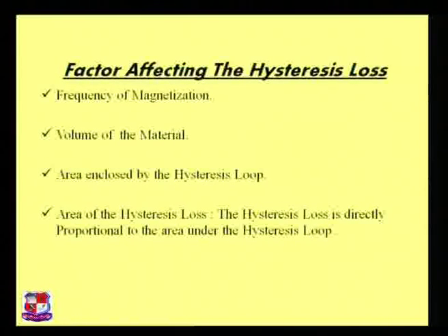Here we can see the factors which affect the hysteresis loss. The first factor is frequency. If the frequency changes, the hysteresis loss will change according to the frequency. If the volume of the material increases, then the hysteresis loss will increase. Then the area also affects the hysteresis loss. If the area enclosed by the hysteresis loop is more, then the hysteresis loss will be more.